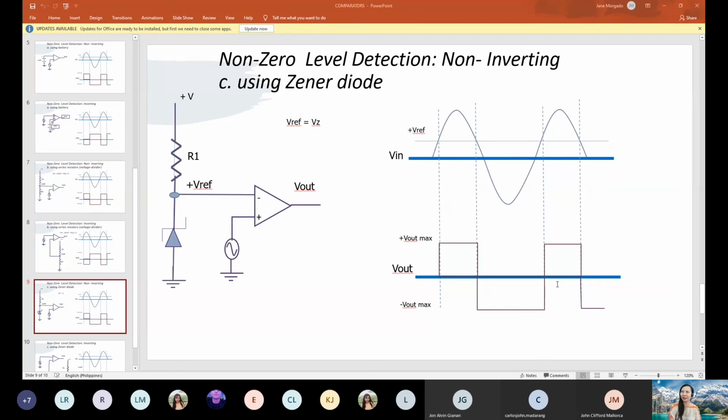Okay, thank you, Carlos. Forward bias: anode to positive, and of course cathode to negative. Positive to positive and negative to negative. Likewise, reverse bias is anode to negative and cathode to positive. That's what an ordinary diode does.